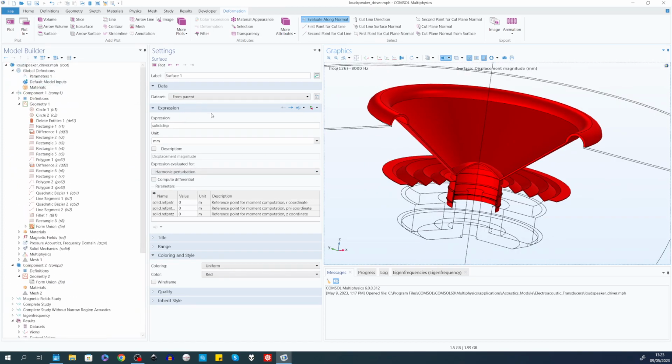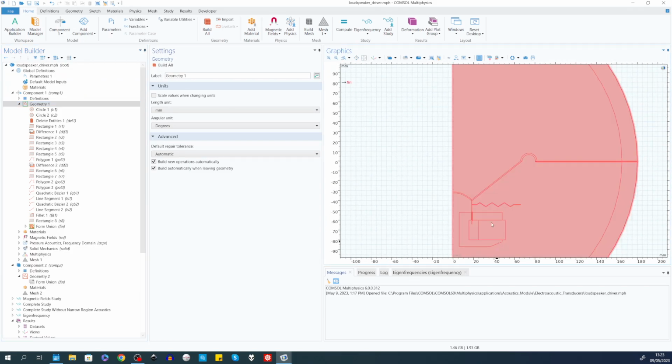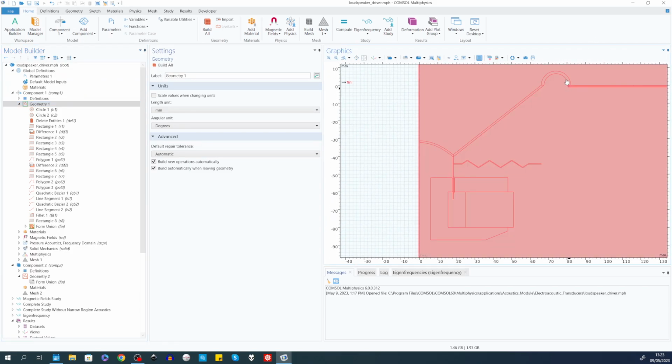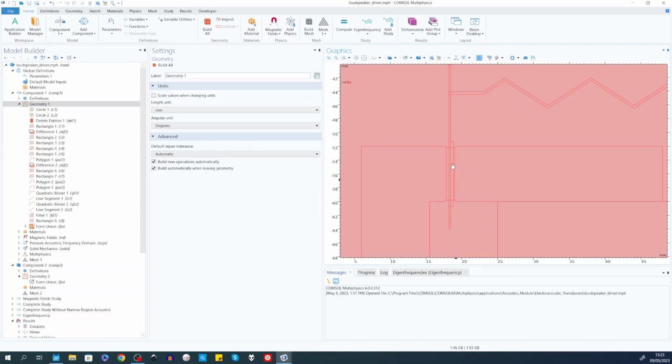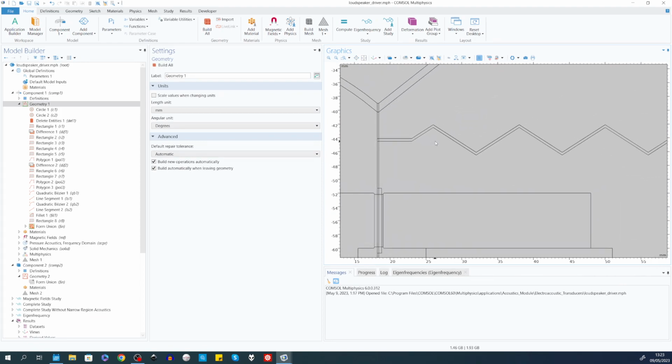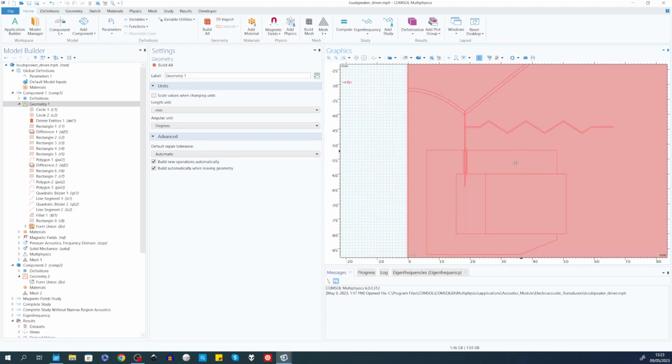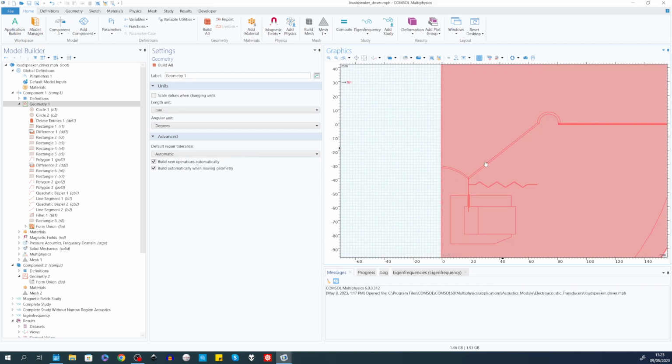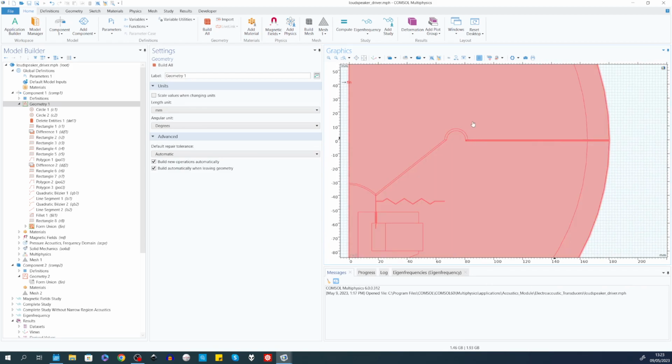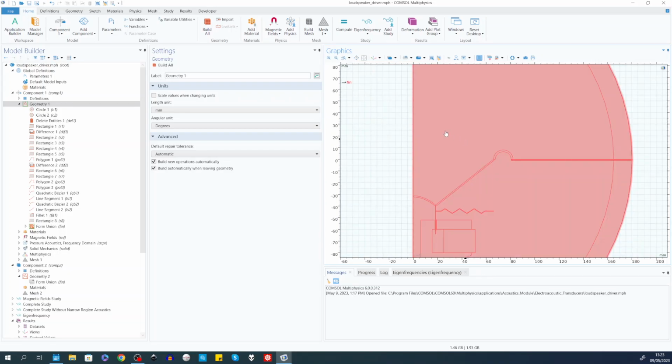So we can build a virtual loudspeaker in a simulation software like COMSOL Multiphysics, like I have here. In this case, it's a very simple 2D axis symmetry case that they have made themselves, and that's what I'm showing here. We see the magnet system again. We have our voice coil, our former sitting here, our very simple spider, and here we have the cone and the surround, and it's sitting in a baffle. So we are measuring or simulating corresponding to a measurement where we have a baffle.